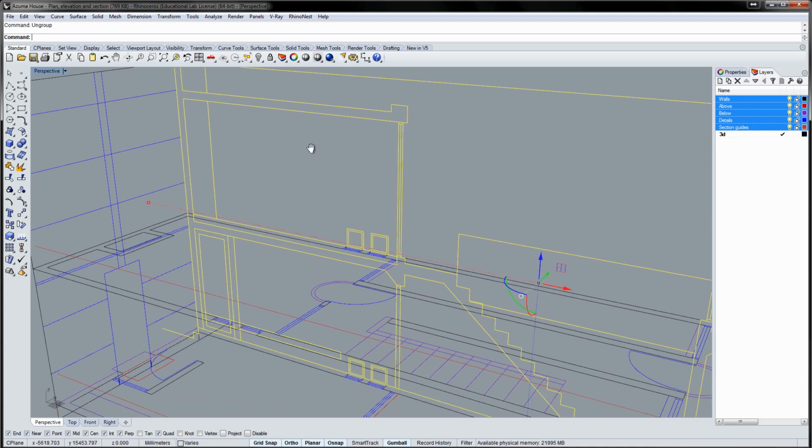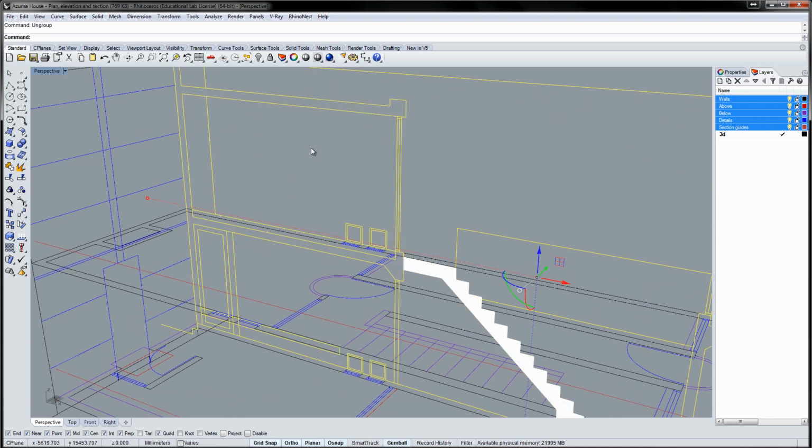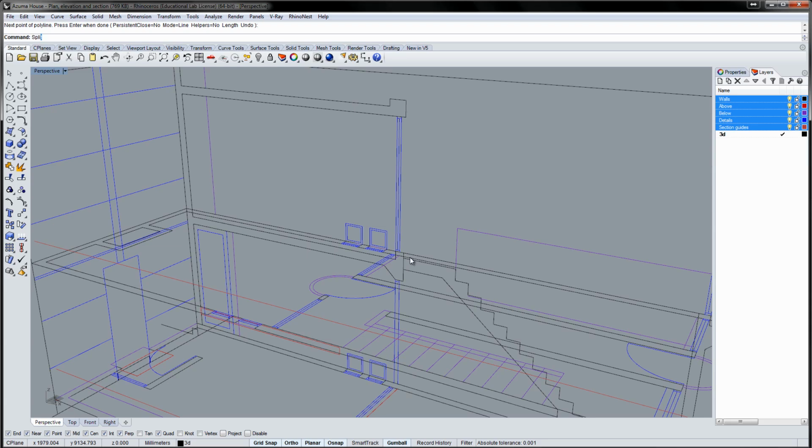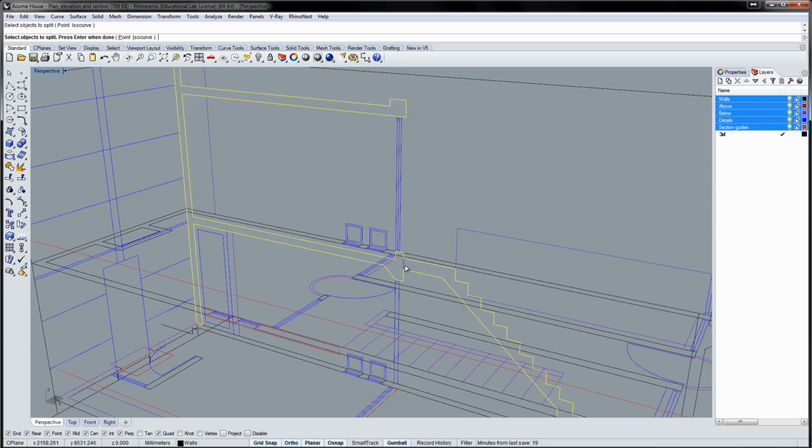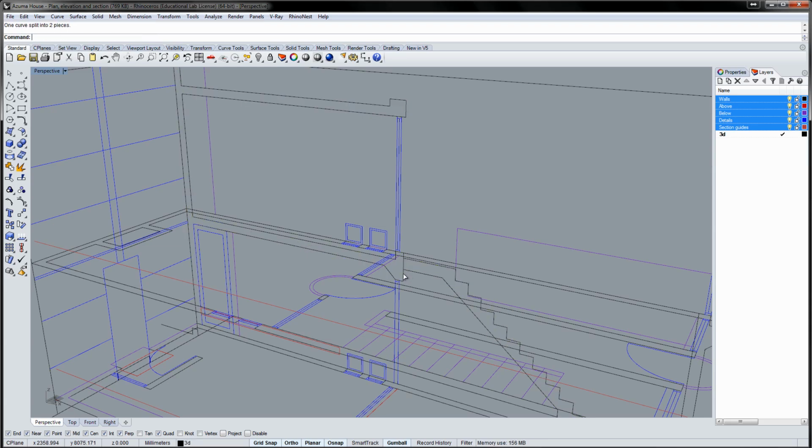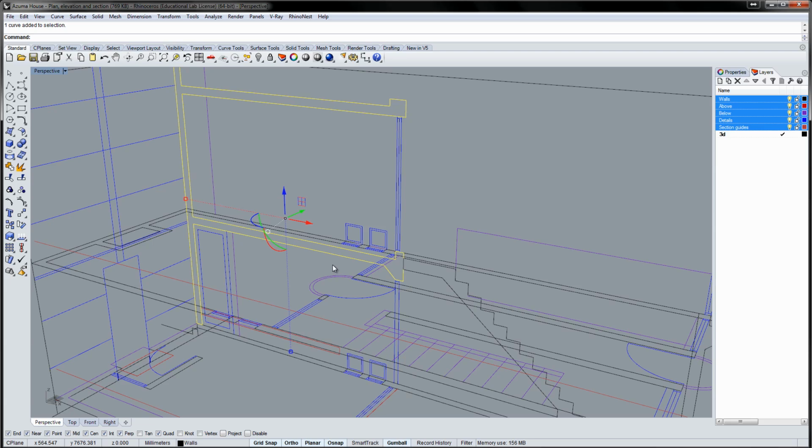Using curves from this section, we will create walls, floors, and the staircase. First, we need to split the floors from a staircase. Draw a vertical line and use it to split the polycurve. This curve is an open curve. It will not produce a solid when extruded. Close a curve using the Close Curve command.